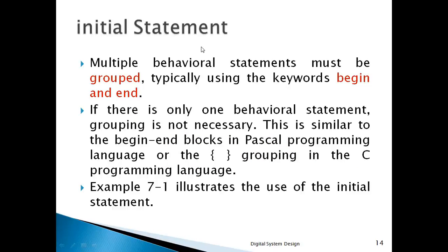Multiple behavioral statements must be grouped using the keywords begin and end. If there is only one behavioral statement, grouping is not required. This is similar to the begin and end keywords in the Pascal programming language or grouping using brackets.